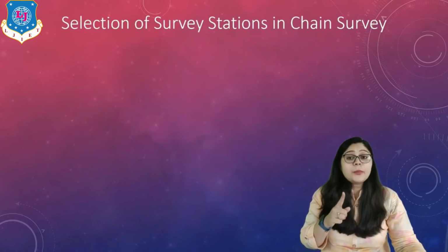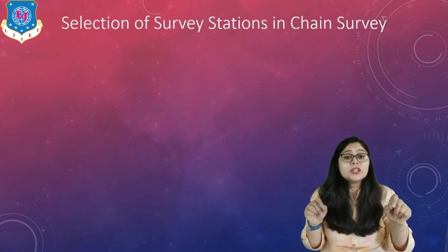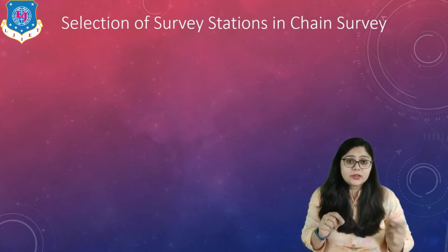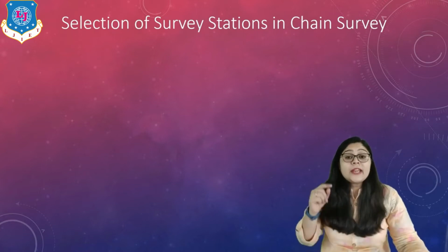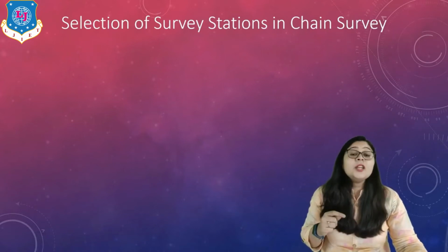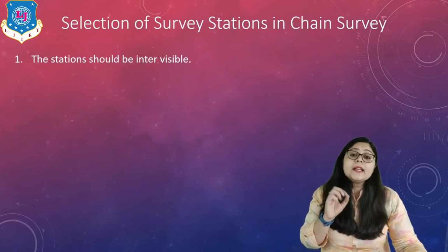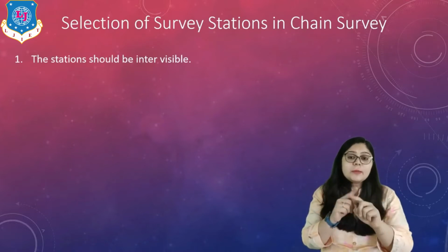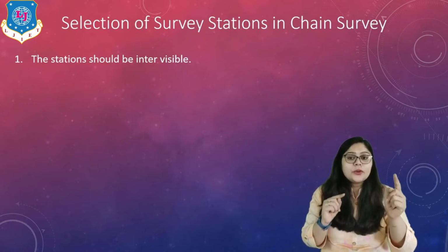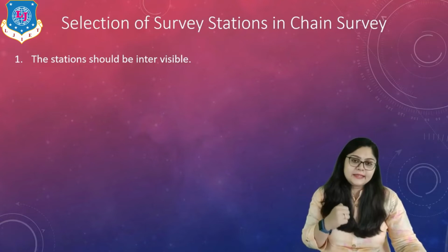So it is very important to select the survey stations. Either it can be main station or subsidiary or tie station, right? So now for that, various points are there that we should keep in our mind. In which the first point is that the stations should be intervisible. It means they should be visible. From one station we can see the other one, so that we can connect the lines, right?